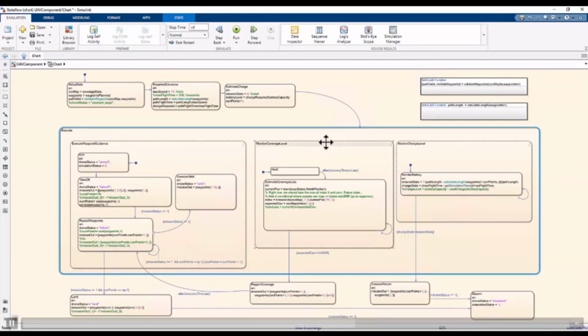And you can see this is Stateflow for UAV behavior. This is a key part of this model. Stateflow is a subsystem in this case, a component. You can define the UAV operational behavior using a state machine. So you can analyze the behavior based on the state, okay? And you can add conditions to move between states.